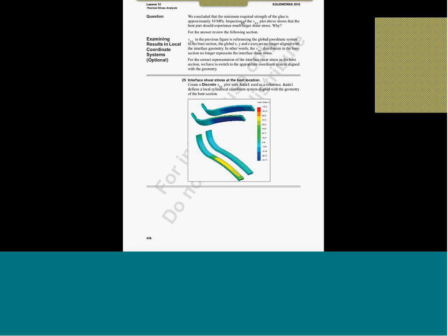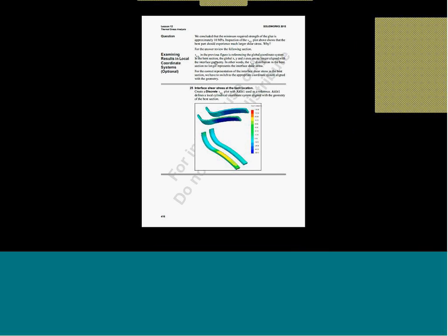Typically, if there are cases where we want to understand if a glue or a weld is enough to withstand these two parts, then we can see the appropriate planar shear stresses, check the values and decide if it is crossing a certain limit or not. And on the other hand, this option of create body from deformed shape. Let me show you where it is.